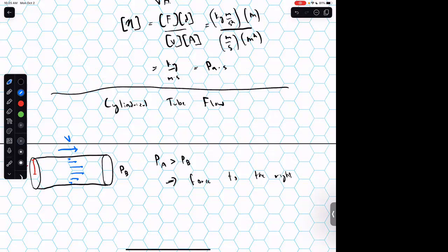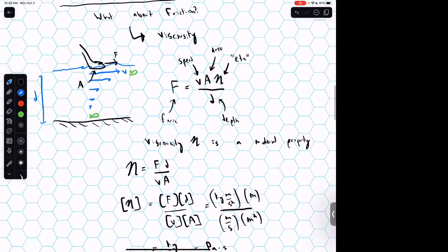So in other words, transport through a pipe isn't just the entire fluid moving as one big plug through the pipe. Really near the edges, it kind of gets stuck because it's feeling a lot of friction from the wall. But as I get more towards the center, the flow will move a lot faster and it has some overall rate at which it's going through. And the intuition for why that happens is if you look at how I define shear up here, you'll notice that the amount of friction force I encounter depends on the depth.